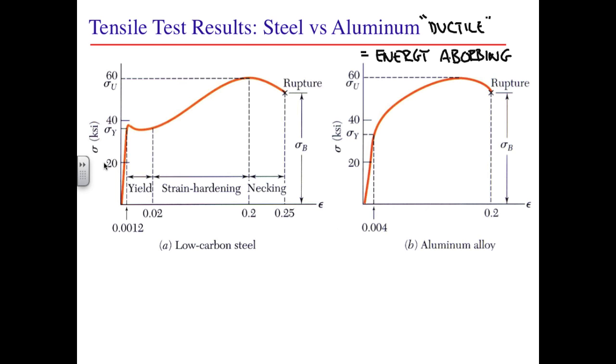For these ductile metals, there is a range of stress and strain at low strain where there is a linear relationship between stress and strain. This is where we want to operate in any structural engineering capacity. This range is also said to be elastic, which is to say the deformation is reversible. If we load the material within this range and then unload it, the material retreats along the stress-strain curve and no permanent deformation occurs.